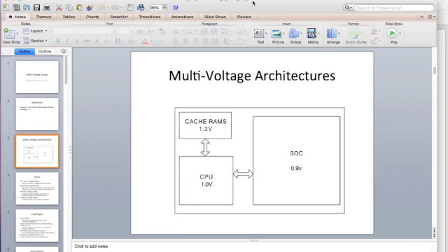Another important portion of the chip where you cannot reduce the supply voltage: there are two places. One is the IOs, because you might have to connect to chips outside which use certain standard supply voltages. So at the IOs you need to be able to transition from a lower voltage on the inside to a higher voltage outside. Another area could be mixed signal interfaces. Maybe you have some analog blocks with digital interfaces, and again there you might have low to high voltage interfaces.